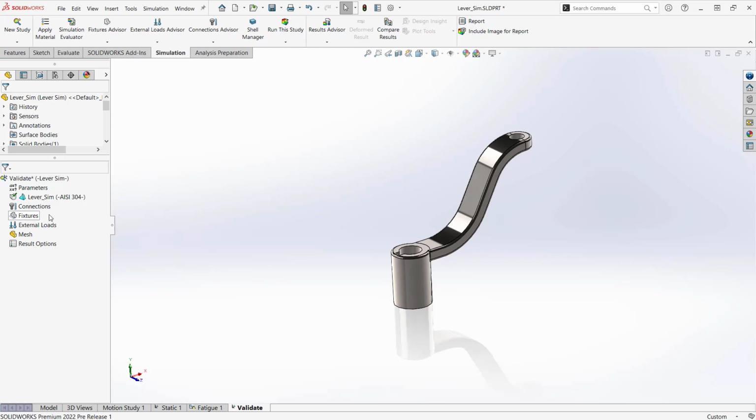Next up, how's this component going to be restrained? Well, in this scenario, what I'm going to say is this little crank handle has actually got a little bit stuck. Now, when we design anything, we always need to consider the worst case scenario. So the worst case for this little crank handle is that it's completely stuck in place. You're trying to turn it and it just won't move. So that's exactly what we're going to simulate.